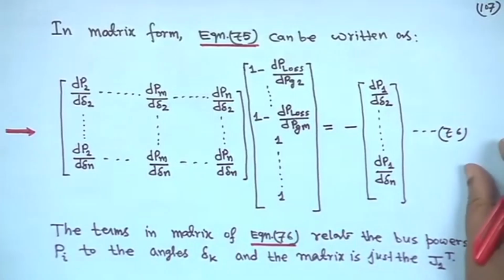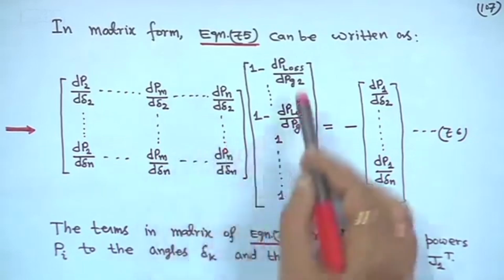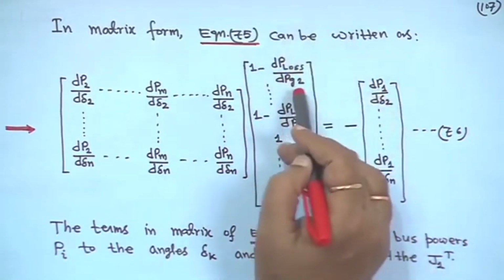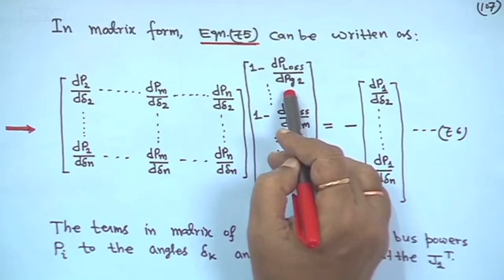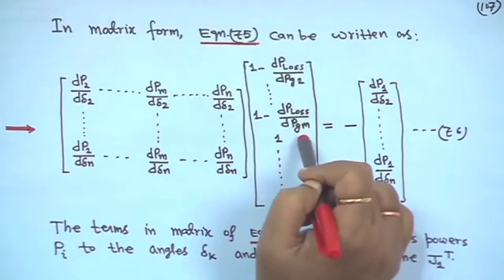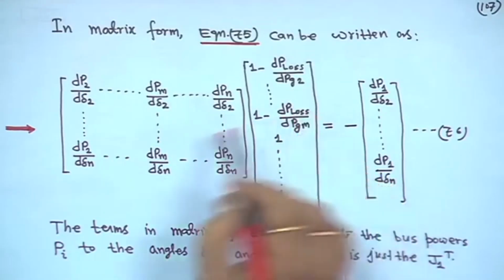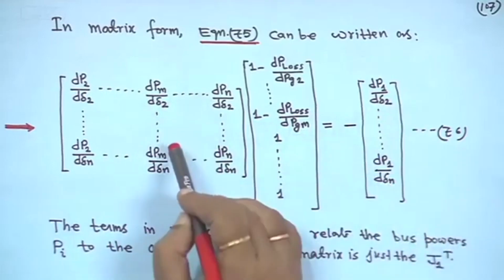So that means, after load flow studies you know everything. So, easily one can compute this, and this is actually the reciprocal of what you call the penalty factor. Penalty factor in general we have taken Li is equal to 1 upon 1 minus dPloss/dPgi, right. So, these are basically penalty factors.